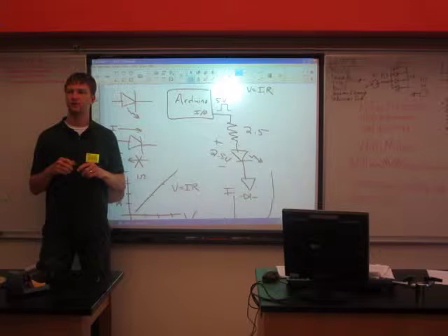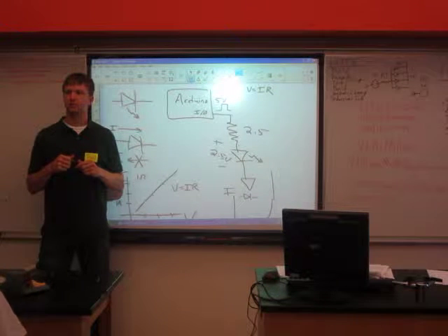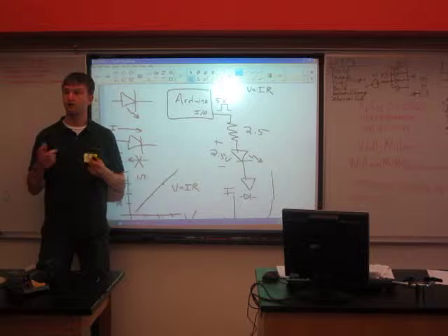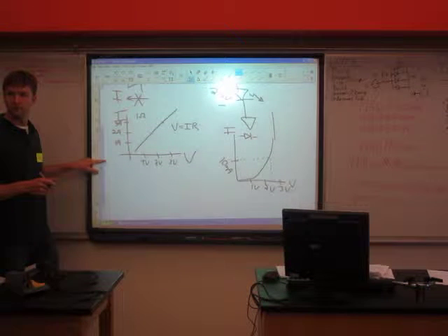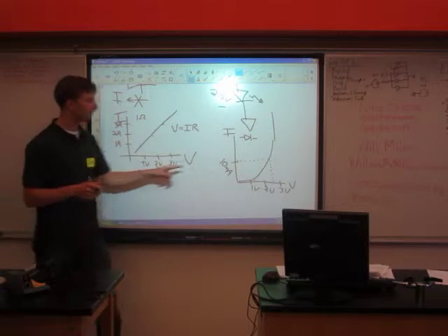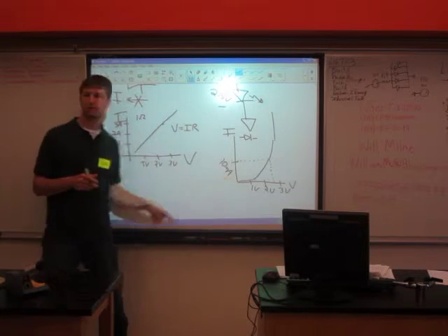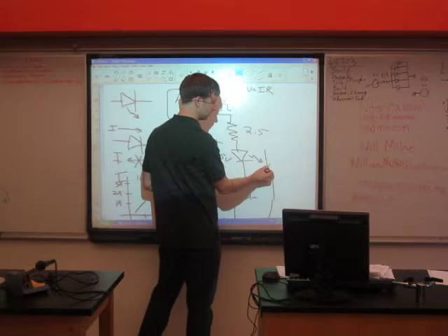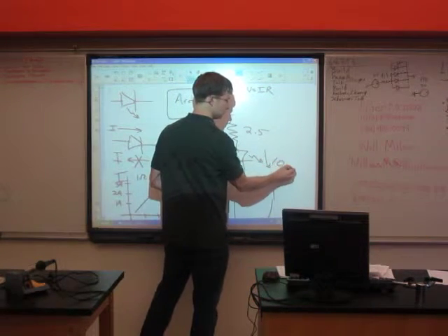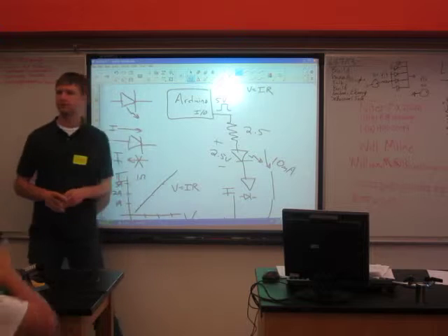You want to know the amount of current you want going into the LED. Right. But we already decided that, right? So then you look at the curve to see what matches. So we already decided 10 milliamps is going through the LED, which is great. You're absolutely right, because we can use that. We know 10 milliamps is going through that LED.